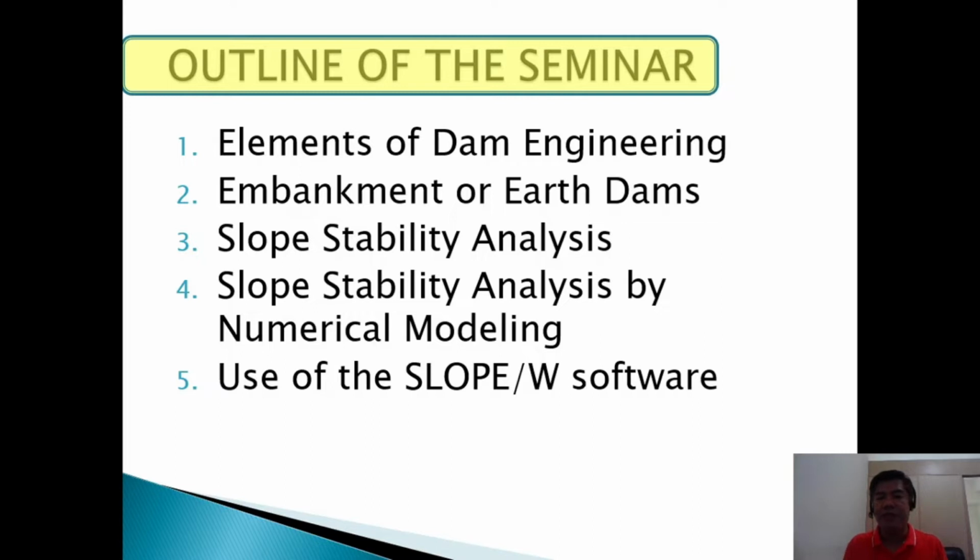So after that overview, let us talk about the theoretical aspect of slope stability, which is actually the method of slices, part of the discussion in geotechnical engineering subjects or in soil mechanics in the old curriculum. I hope that you have learned it in the classroom, the method of slices, in which the original theory is the Swedish method of slices.